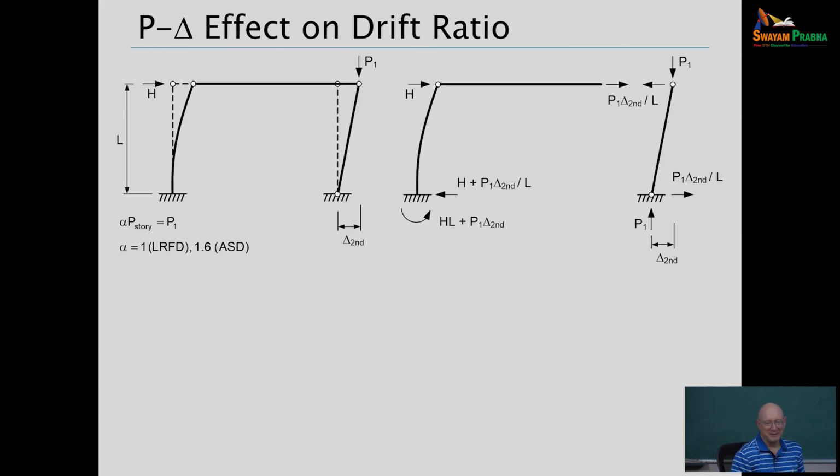It failed ballot in the last ballot, I guess that would be for the 2027 ASCE 7. But now in the ballot that was for the last one for 2027, it just passed in November. They were able to get the problem sorted out. One of the solutions, and the solution that failed, was kind of a clever solution. So we have LRFD load combinations that have a more scientific or probabilistic basis. Some of the ASD combinations were kind of more historical, so that's where things got all messed up.